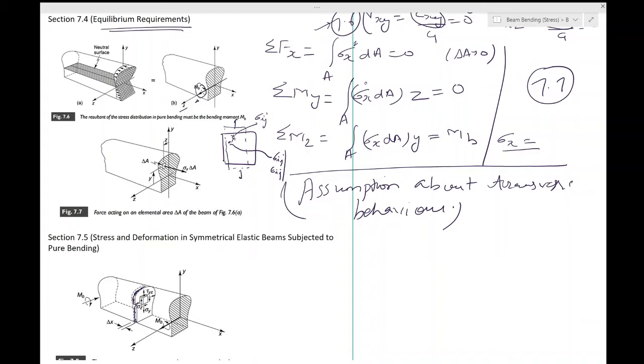Now the slenderness of the beam, remember this is one word which we used earlier on in this chapter, our slender beam, suggests the plausibility of assuming that the transverse stresses sigma y is equal to sigma z is equal to tau yz is equal to 0 throughout the interior of the beam. So sigma y, sigma z and tau yz.